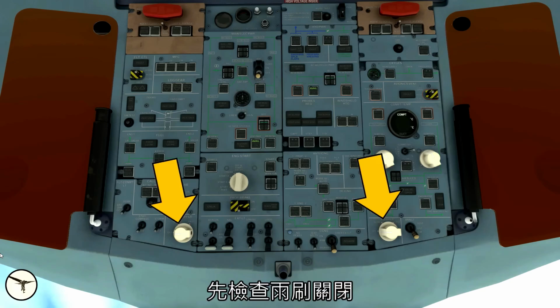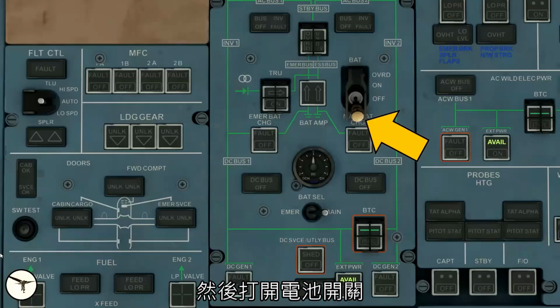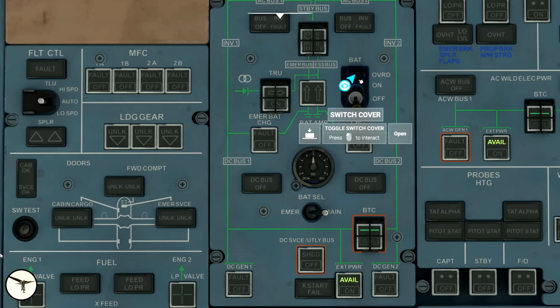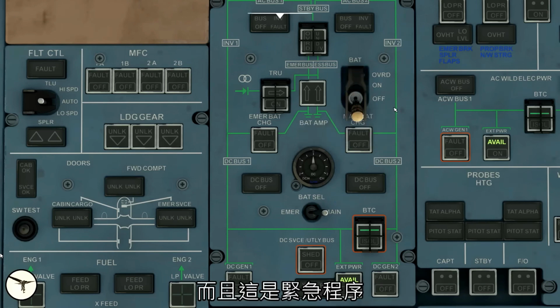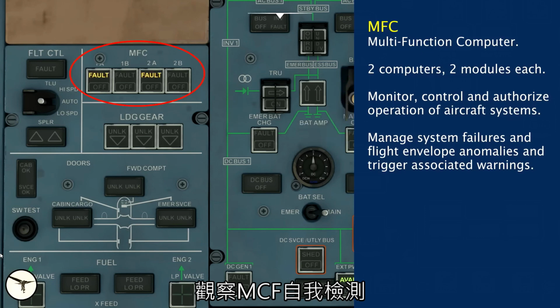First, we check that the windshield wipers are off. Then we are ready to select the battery switch on. You shall not lift the guard. This is only needed to activate override mode, and this is an emergency procedure. So battery on. Observe MFC self-test.